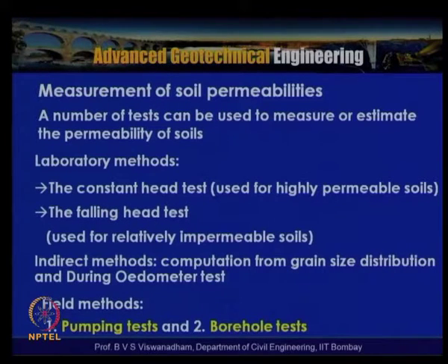Also, from the oedometer or consolidometer test, when the soil is subjected to consolidation, indirectly we can compute the permeability based on the coefficient of consolidation, the coefficient of volume compressibility and the unit weight of water. These are the possible laboratory methods.